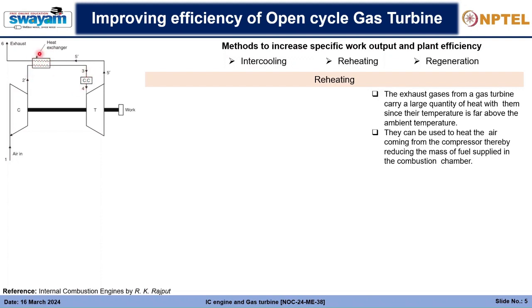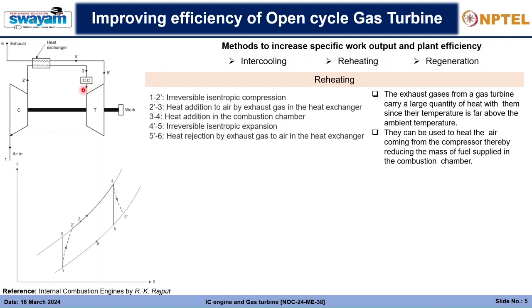If this happens, the basic concept is to transfer the heat to this region, and accordingly a higher amount of heat will be available before reaching the combustion chamber. Hence we will have to supply a lesser amount of fuel or lesser amount of combustion energy in order to attain the same position like in 4. So the T-S diagram will be very helpful to make us understand this.